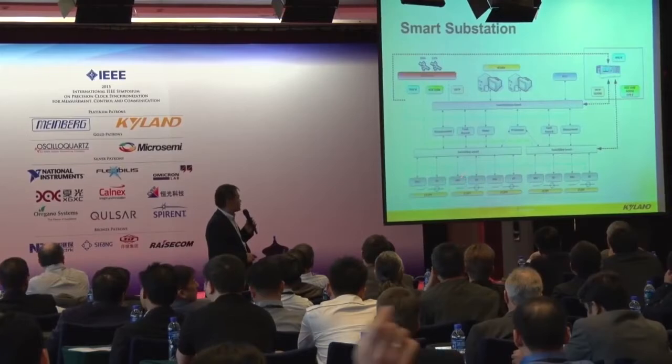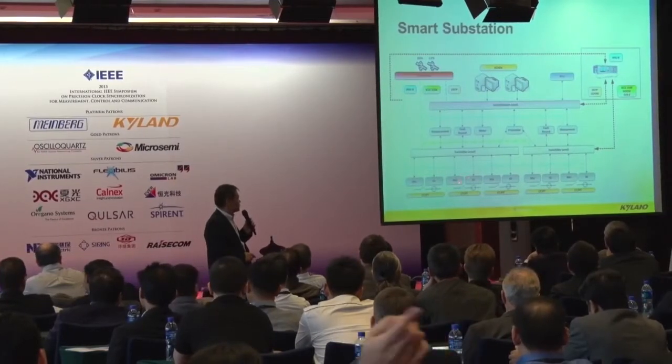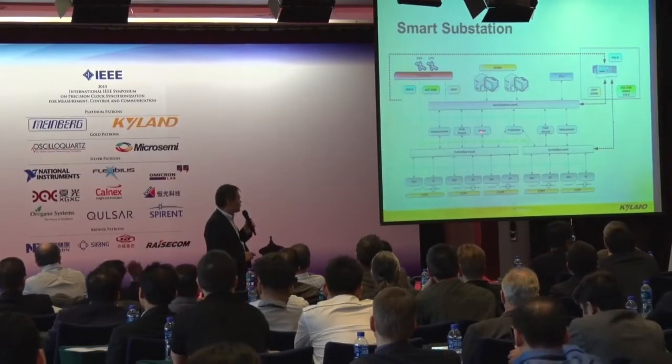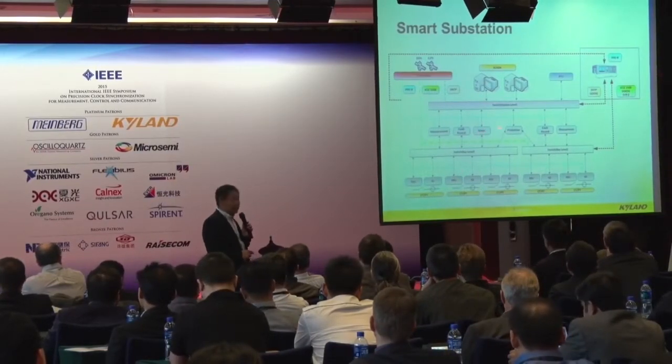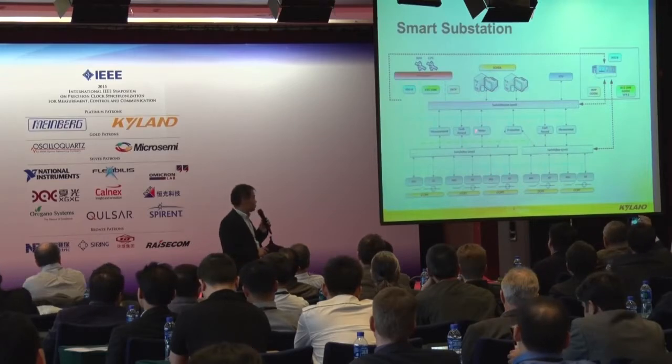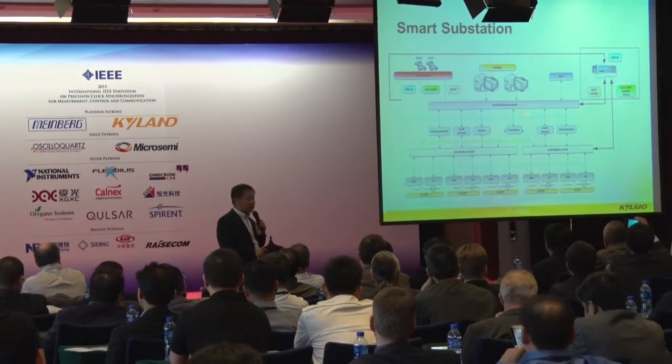If you lose time synchronization, the IED, especially the protection relay, gets into big trouble, and may even misoperate